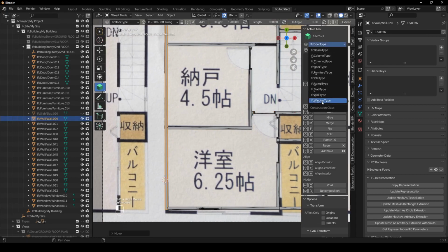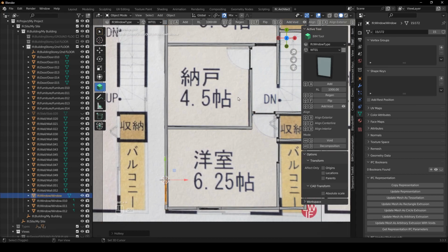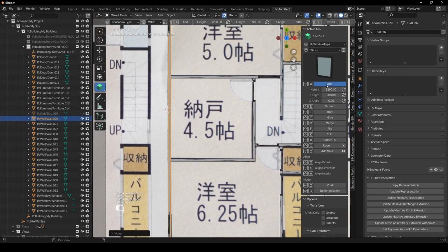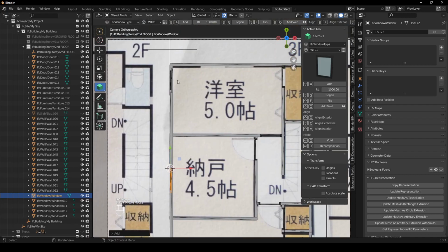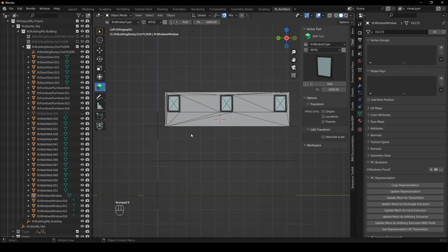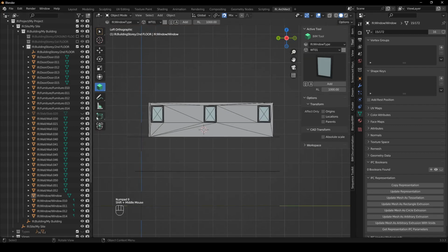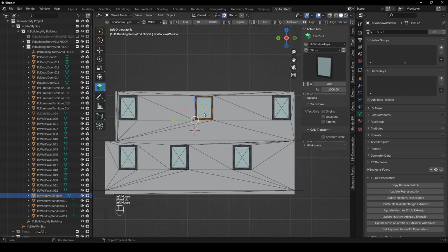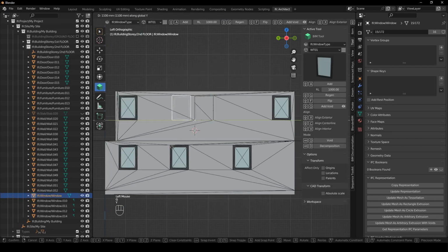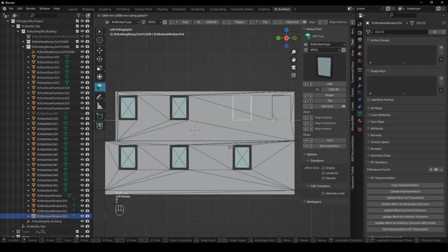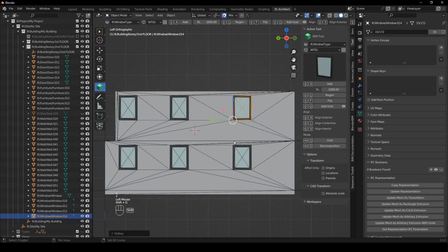We're going to go to our window type, and we're going to say Shift A, and we're going to go here, and we're going to say add, and we've got a window there. We press 3 on the numpad and press 9. It'll swap around our position. So if we activate our floor below, we can check where our windows were and line them up. So I'm just going to say G Y and Shift G. And take this one and say G Y and Shift G.